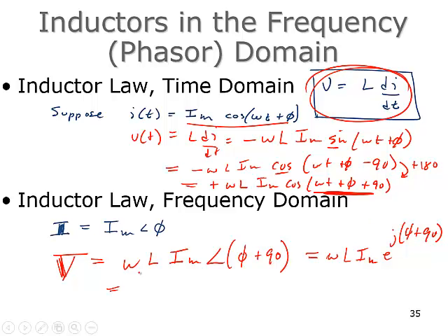And you can then, stop me if you've heard this one before, you can split those apart, right, because they're exponents, right? And e to the j90 is what? In the complex plane, you're 90 degrees away from the origin with a magnitude of 1. What are you at? If this is 1, you're 90 degrees.